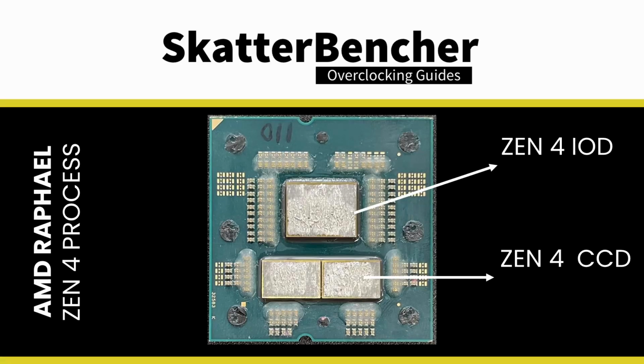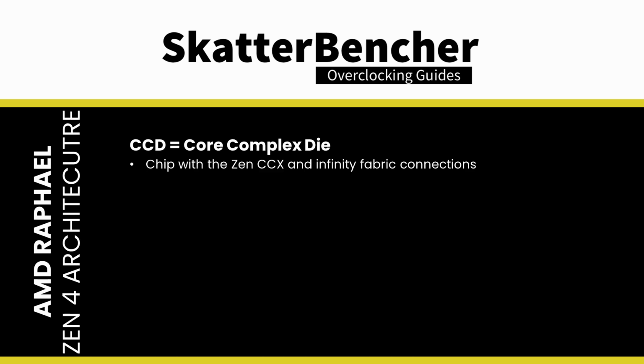What's important to note though is that the processor package, the physical part, is not really that much different from the Zen 3 Vermeer CPUs. Depending on the specific SKU, you'll find 2 or 3 chips on the CPU package, 1 or 2 CCDs and 1 IOD. CCD stands for Core Complex Die and is simply a chip with the Zen CCX and Infinity Fabric connections.